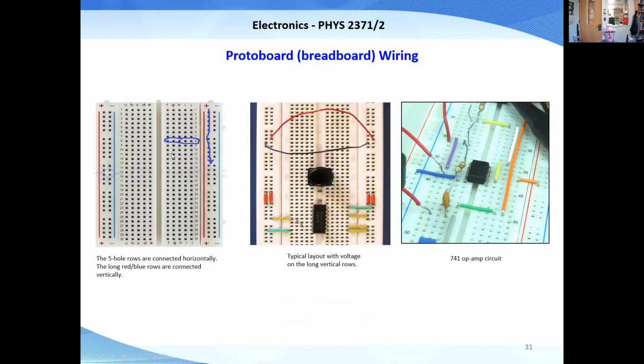I guess you've had a little experience with the breadboards, right? The proto boards. These 5 pins are connected underneath, but they're not connected to these 5 pins that are connected. And the vertical pins are connected. And you're going to put your chips across this valley here. So then you can connect, like, this pin here to the green wire. And that's what your 741 looks like.